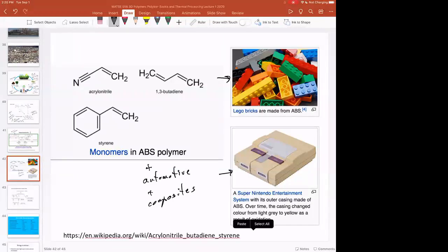And so just talking about PLA, PET, which is a tough polyester, and ABS, we've covered a lot of the consumer plastics out there, aside from polyethylene and polypropylene, which are the most consumed plastics. But we don't additively manufacture a lot of polyethylene and polypropylene yet, because they're used a lot in cheap plastic stuff for injection molding. But ABS is an engineering thermoplastic.